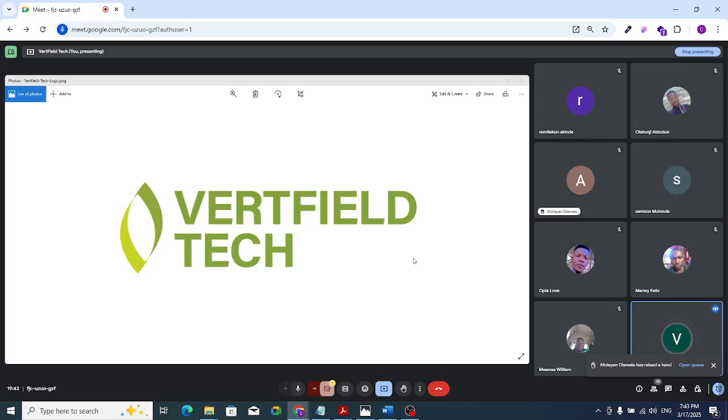What you need to do is, in that 5 kVA that the system can power up, make sure that some of those important appliances or loads have been already designed and included in that 5 kVA. Go ahead, advise the client to install the 5 kVA. If he agrees to your recommendations, install it. Then how he will be able to run the system is that if there are other important loads he wants to add to that system, he can then run them one after the other.